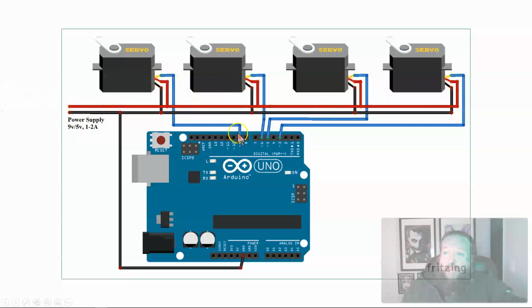And then your control lines, you can see here, they have one on pin 9, and then they have the others on other PWM pins from there. But here we still have to know that if we're using Servo.h to control these, then this pin cannot be used for any analogWrite or anything else.